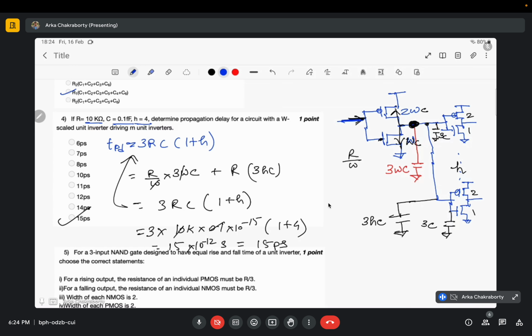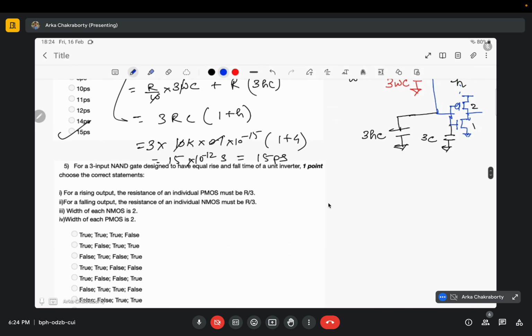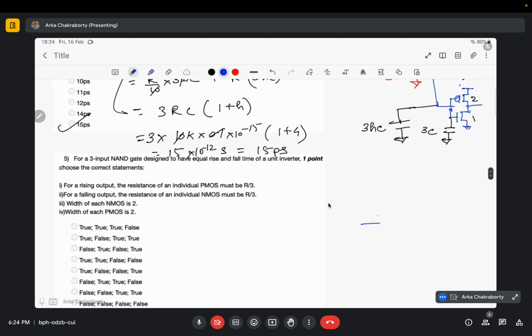See, if you remember in the last class, I told that there are multiple capacitances present in a MOSFET, right? If this is my MOSFET, how many capacitances are present in it? There are basically five types of capacitances present. It is my gate, it is my drain, it is my source, it is my body. Remember, there are three oxide related, that is gate related capacitances, and three body related capacitances, and two of them are common, so there are total five capacitances.